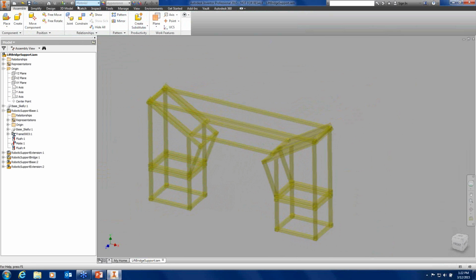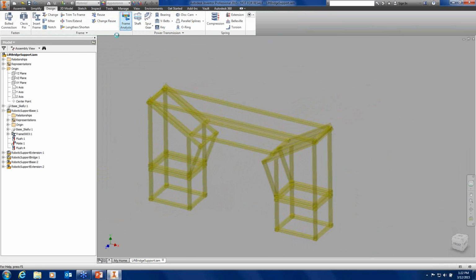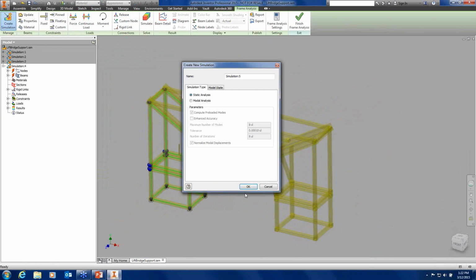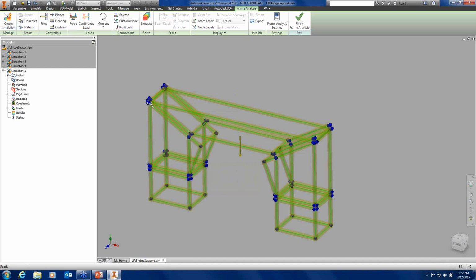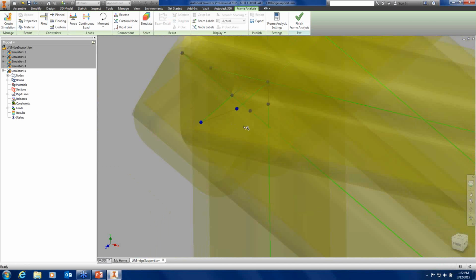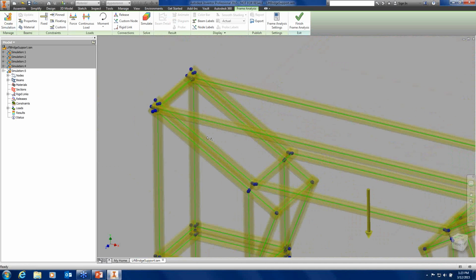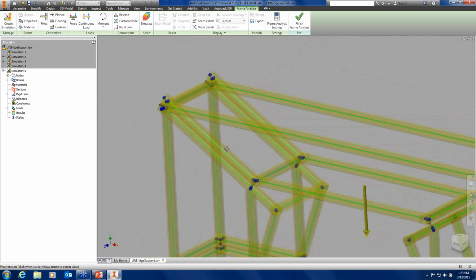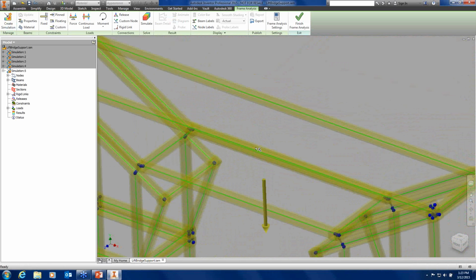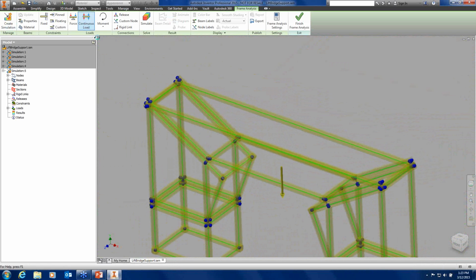I've got to get in there and actually create the assembly. Frame assembly. Create it based on the given geometry that's in there right now. Let that think a moment. So now, a lot of extra nodes, okay, which could start giving you some headaches. I have had at times to go in there and figure out where rigid nodes were selected and put together that shouldn't have been. But here in this case, I'll do a continuous load layout.